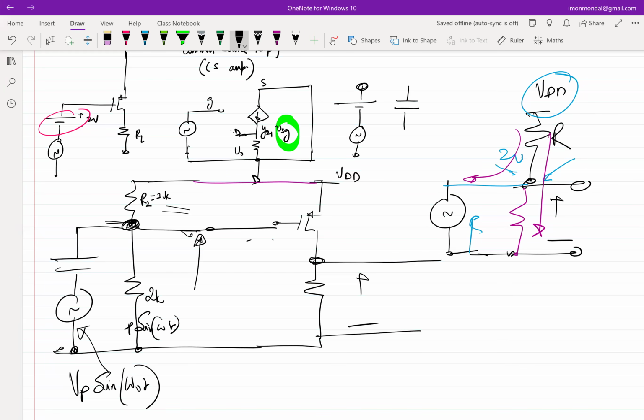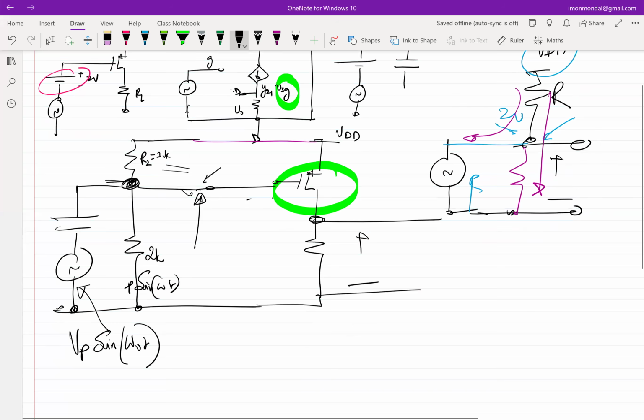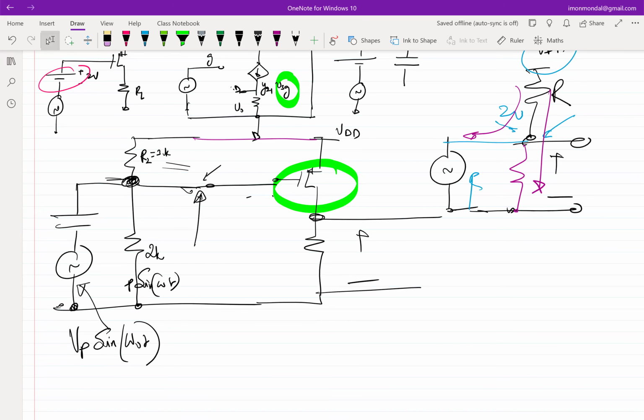Now, can you tell me whether the existence of this device will affect that voltage? No, right? So basically that voltage is out of the equation. Now we'll have to find out what will be the voltage at this node. So what should I do to figure out what is the voltage at that node? Steady state, sinusoidal steady state analysis. So what I can simply do is go into the phasor domain and find out what the voltage at that node is, right? If I have to do a phasor analysis, what needs to change? What should I replace here?